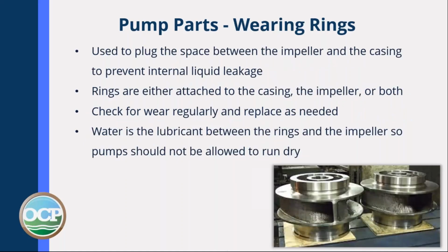Wearing rings, these are used to plug the space between the impeller and the casing to prevent internal liquid leakage. The rings are either attached to the casing, the impeller, or both. Check for wear regularly and replace as needed. They're called wearing rings because they're made to wear out, so you replace them to protect your pump. Water is the lubricant between the rings and the impeller, so pumps should never be allowed to run dry.